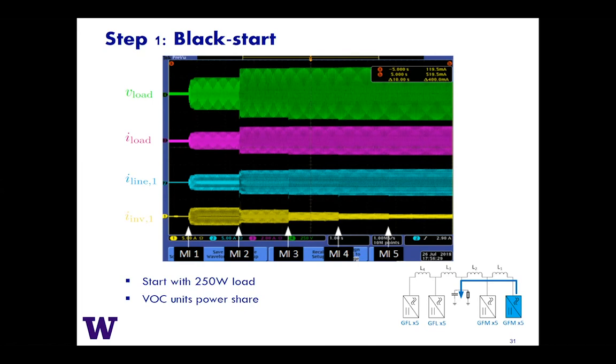and it's a pretty heavy reactive load. And so we actually had to be very careful so that when that first unit turns on, it's not overloaded by the reactive power load across the system. And a big bulk of it was all the filtering elements on the outputs of the inverters. So anyway, that was a very contrived and controlled thing that we had to do with a very light load. But yeah, there's lots of work yet to be done on how to do this gracefully.